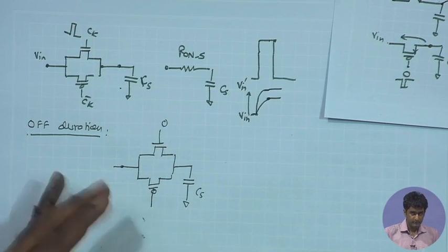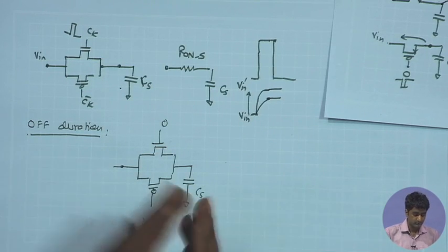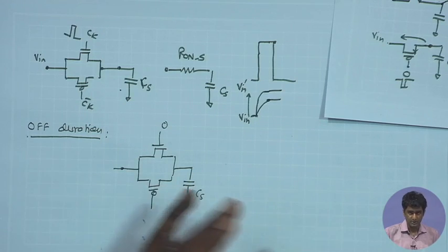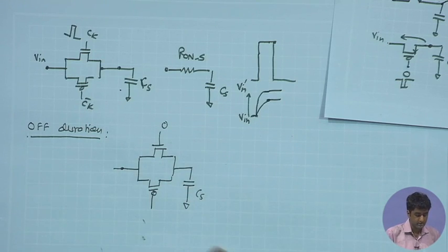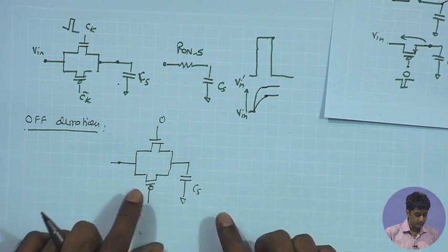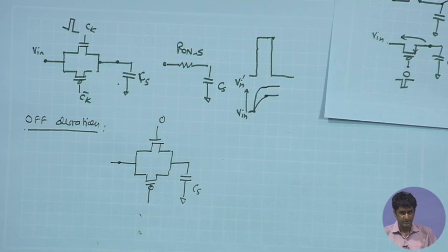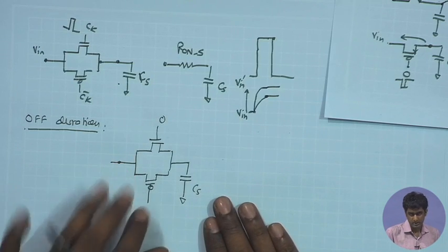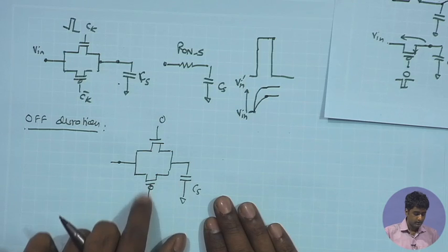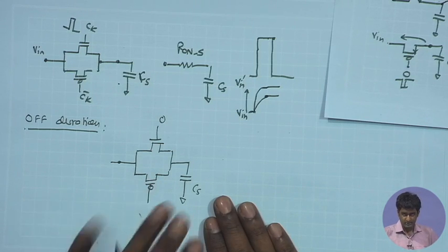So, in the MOSFET we have several components of leakage, several ways in which the leakage current can exist. We have subthreshold leakage, we have junction leakage, we have gate leakage current. So, we have to see which one is dominant. If we talk about say 180 nanometer CMOS technology which we are using in our simulations, there the subthreshold leakage will still be relatively small, gate to substrate leakage is yet smaller.